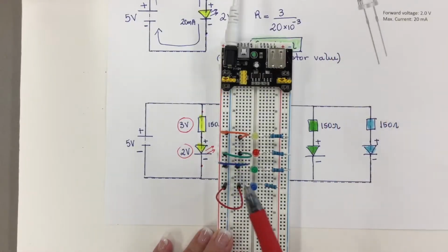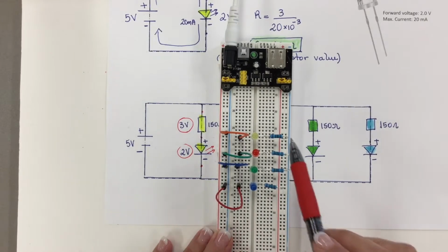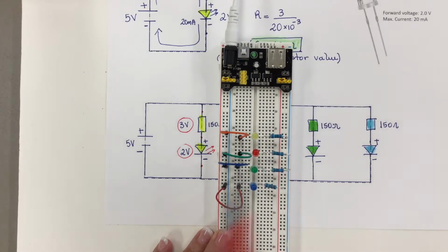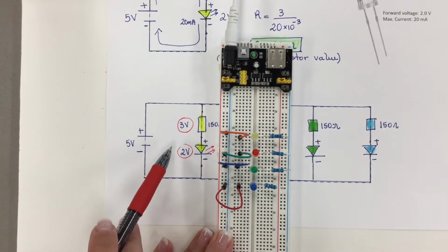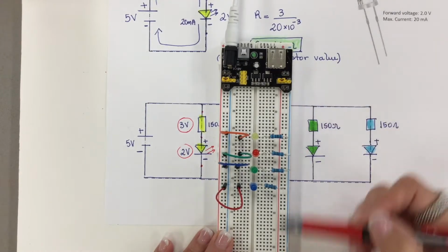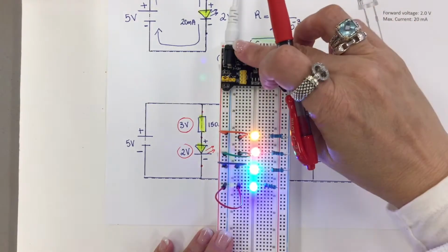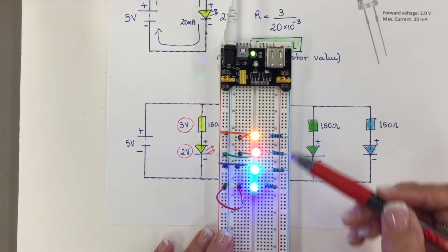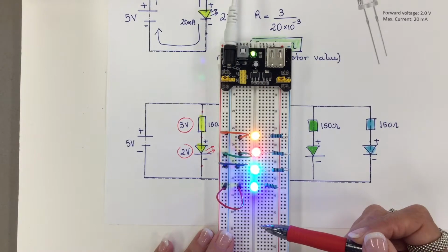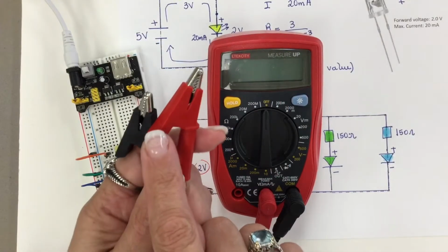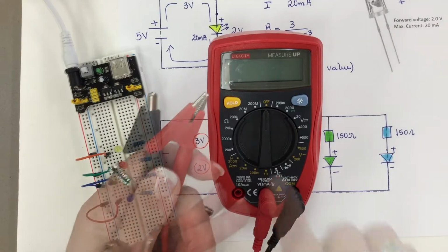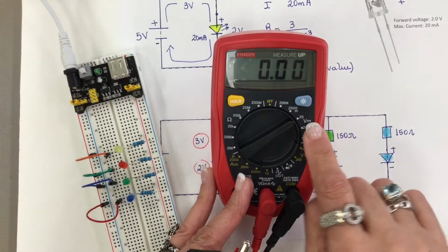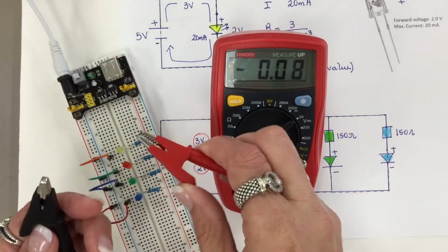I want to use the multimeter to verify that the voltage across this resistor and the voltage across this LED are these numbers. First, I need to power on this LED. In order to measure voltage, we need a current flow in the circuit. I'm using these terminals for the multimeter. I will select 20 volts DC, connect the terminal